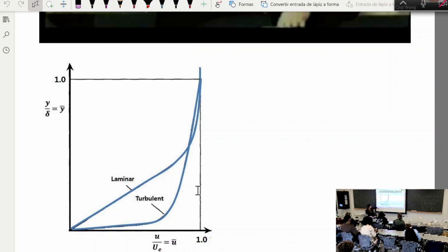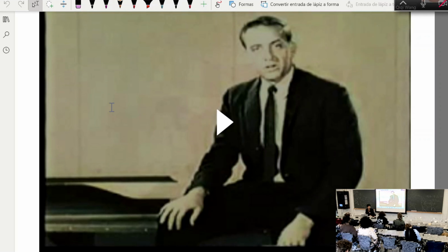So a turbulent boundary layer under the same thickness usually has at least several times higher wall shear stress than laminar boundary layers. Okay, and so this is the first consequence you are going to see: when the flow transitions into a turbulent boundary layer, the friction on the wall increases a lot, and if you care about heat transfer, the amount of heat transfer also increases by a lot. As a result of that, there are several consequences. One consequence is the drag is going to increase, right? Drag due to skin friction is going to increase.